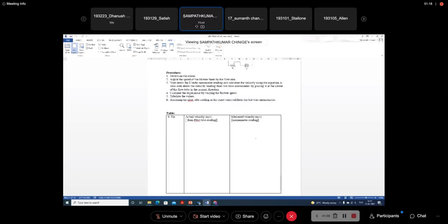Once you get the constant values, you will take that and put it before any instrument or any flow condition whose velocity is not known. Already we have calibrated it, it's working fine, we know the A and B, so directly you can put in A and B, and the current value and R value will be known, so automatically you'll find the velocity. So the I and R values are not required. A and B you have to give as an input. The instrumentation will calculate the current and the resistance automatically. Only A and B have to be given as input. Once you give that, it will automatically take.